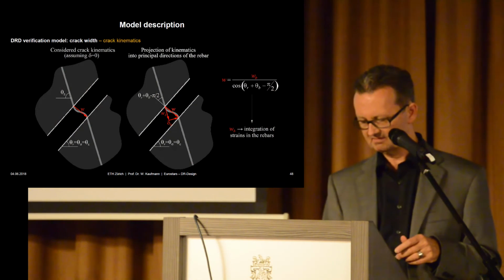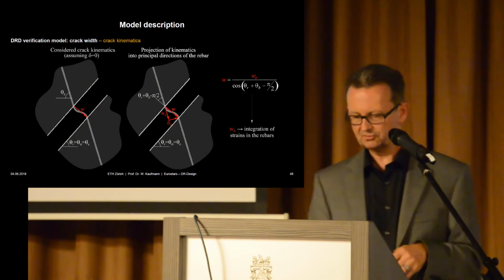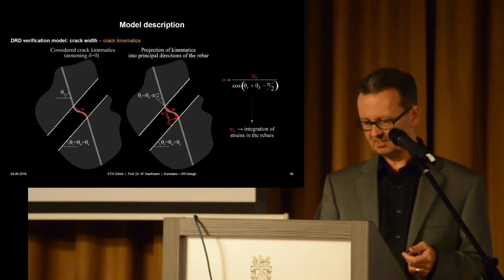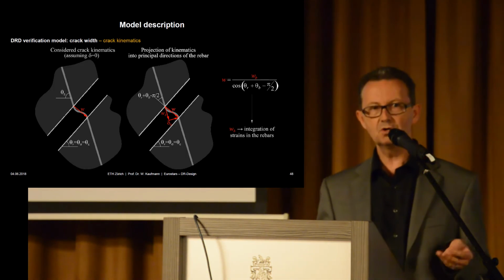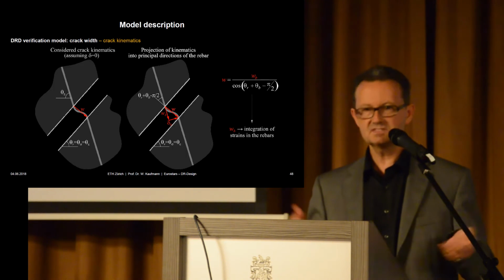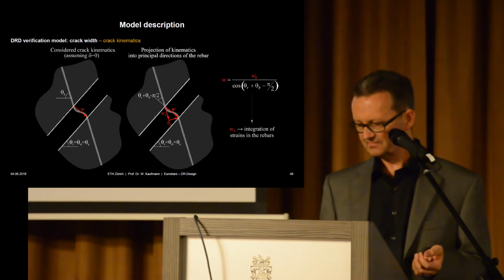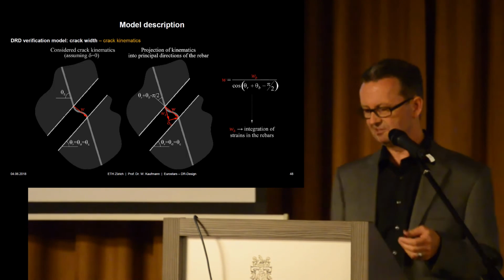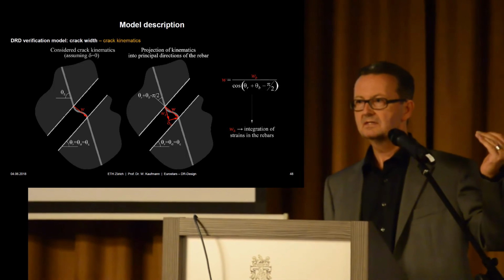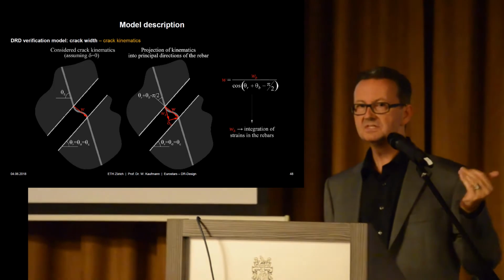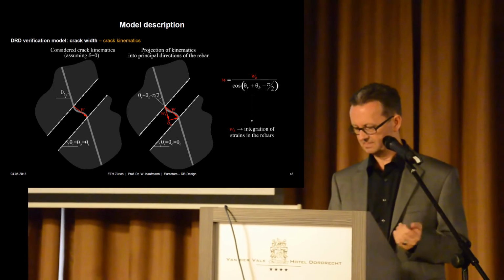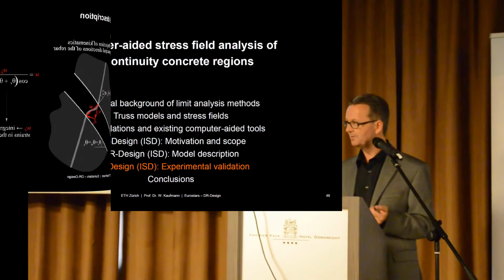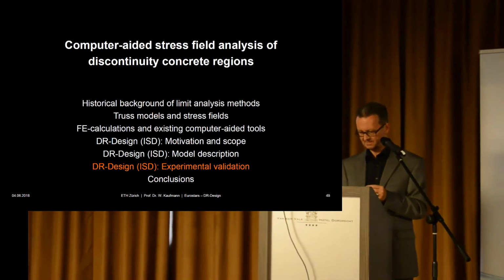Okay, then, well, a detail on how we calculate crack openings. Say this is the crack opening, orthogonal to the crack. We calculated along the rebar, so this is what we get from the tension cord, if we treat each reinforcement as a tension cord. And then, of course, we have to transfer that, and actually, the crack opening is a bit larger than the crack displacement aligned with the rebar. So we get this, it's the value that I showed before, and actually the crack opening is 1 over cosine times bigger.